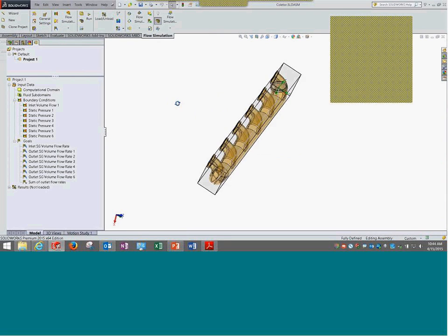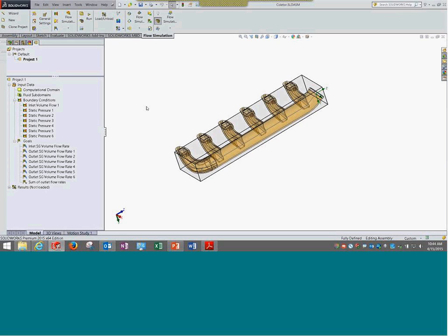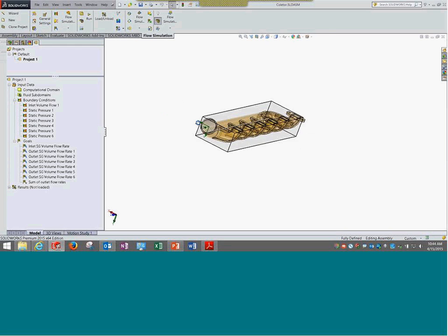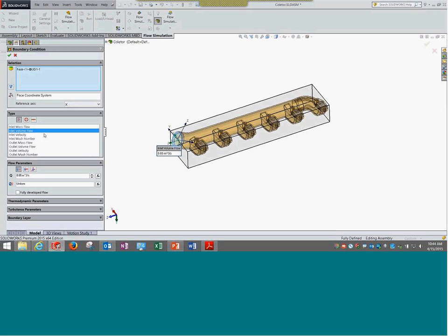Because I don't have the patience to use these boundary conditions over here, I will jump onto this study. In this case, a flow rate is given at a certain surface: 0.05 meter cube per second, and no other changes are being done.